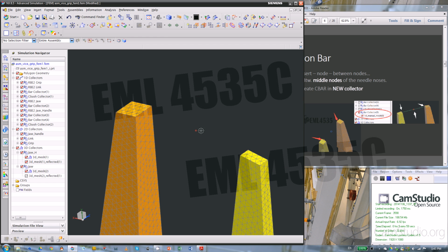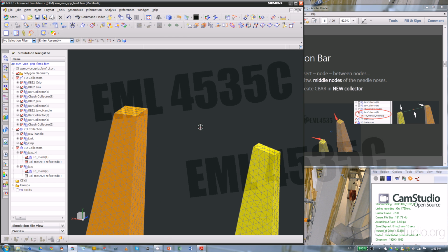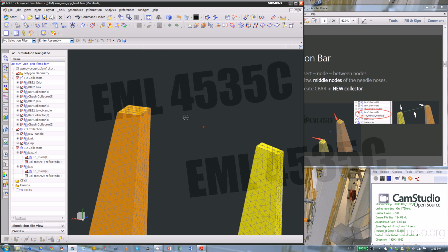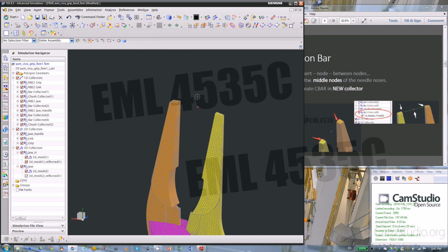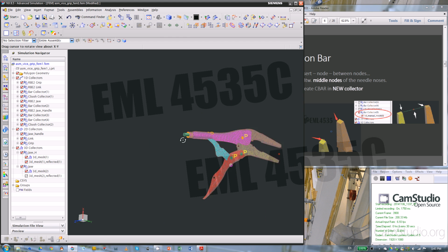The C-bar can rotate on the solid because the solid doesn't have degree of freedom on 4, 5, and 6. So even though later on we're going to constrain the C-bar, the solid will not be fully constrained because they don't have a degree of freedom on 4, 5, and 6. So you can't constrain them this way. That's why we needed a second constraint to prevent this whole thing from rotating.